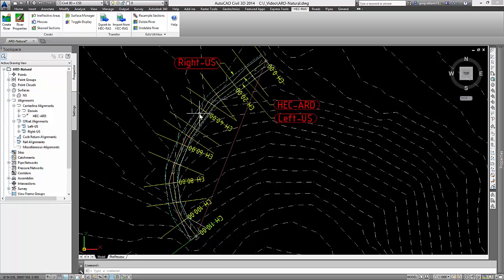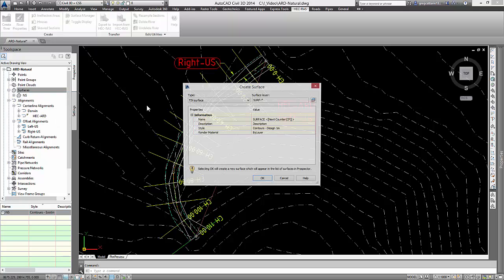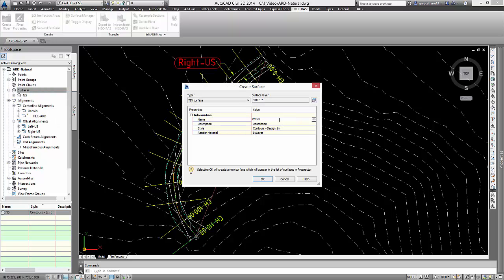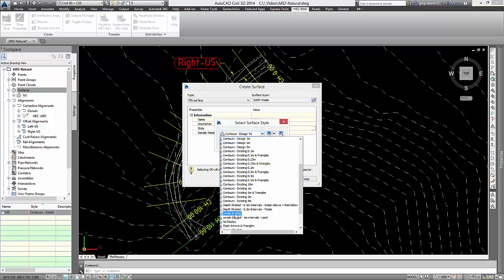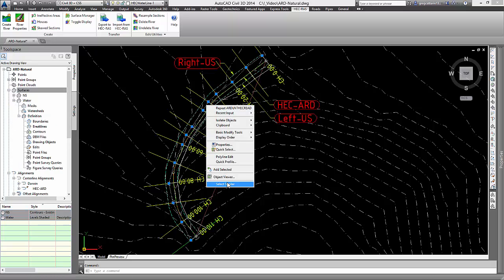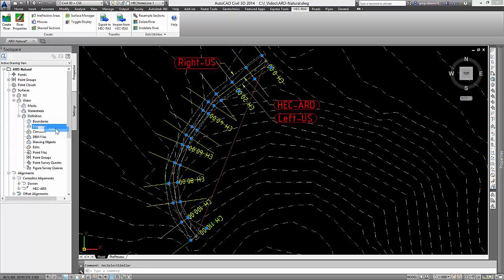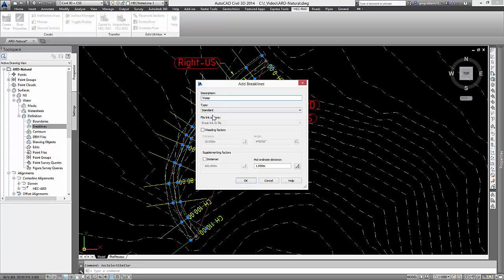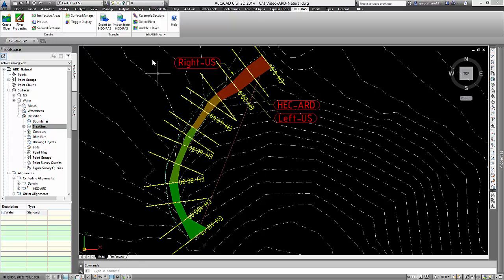3D polylines will then be created in the drawing, across the river at each and every section, as well as two along the river water's edge. These polylines can then be used to create a surface. So, create a surface, then add these 3D polylines as breaklines. The surface can then be displayed in various ways based on styles. Level shading is currently shown.